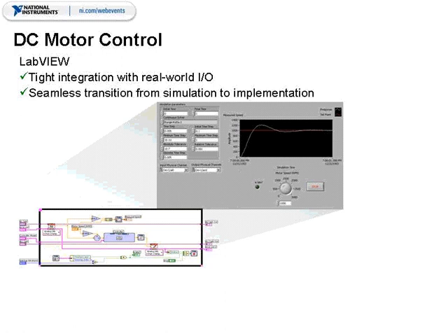To summarize, this simulation module together with the LabVIEW real-time module allows a tight integration with real-world I/O, either through DAQmx functions and data acquisition boards, as we just looked at in the demonstration previously, or using LabVIEW FPGA technology with our Rio and CompactRIO hardware platforms. Overall, this provides a seamless transition from offline simulation to real-time implementation, in which case the same exact code is being used in both cases, and a LabVIEW simulation diagram can be reused both from the offline simulation to the real-time implementation.